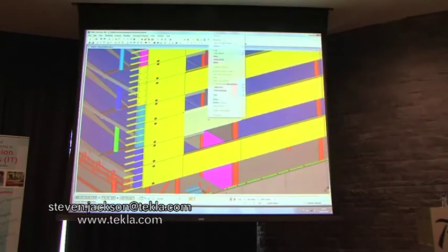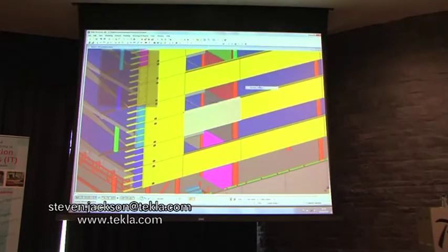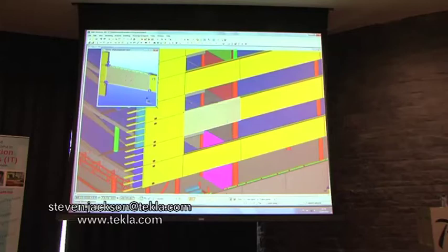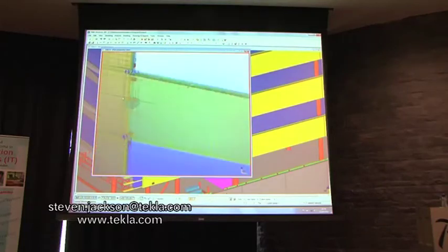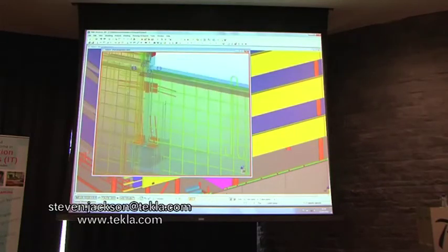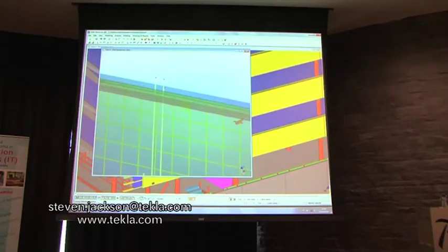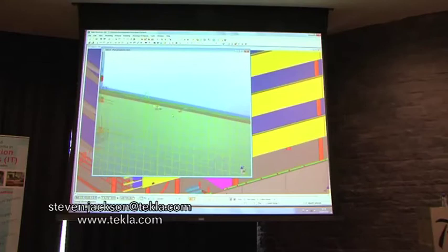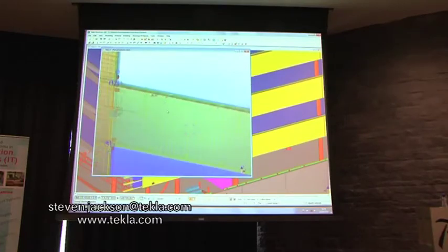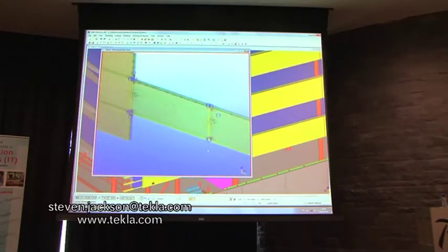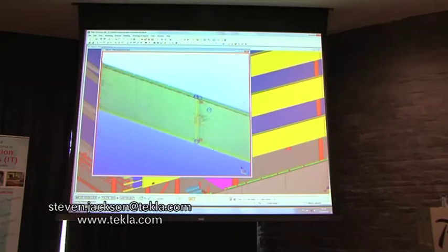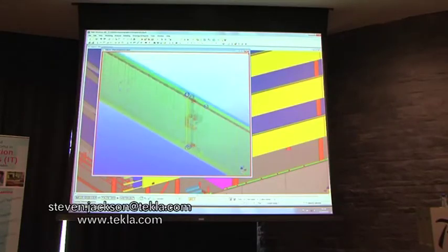And if I just create a 3D view of this, inside there what we have is all the reinforcement, all the hardware, all the weldings required. We have some lifters, we've got the bracketry, we've got sockets for connecting things in there. So literally, the detailers can put absolutely everything required for fabrication and for the construction into these models. So it's a very concise and very precise as-built model with everything in there.